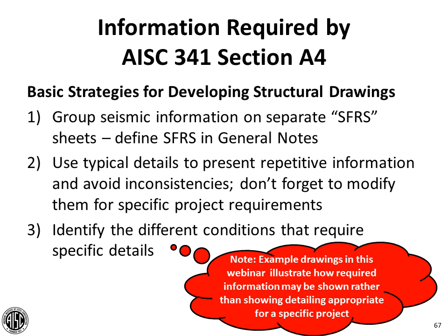One of the things I'll point out is that the great strength of the typical detail is that it does provide this level of consistency. On the other hand, there can be a great temptation to assume that a typical detail applies to a project when it actually doesn't. So you need to make sure that you modify those for the specific requirements of your project, and then identify the conditions that require specific detailing.